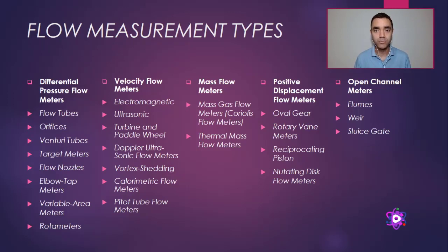The flow meters will perform the calculations, and for the same mass that you have in your process, if you change the pressure and temperature, the information of flow will be different. So when we are dealing with process operation, most often, depending on how critical the information of flow is to the process, we have the compensation of the values.